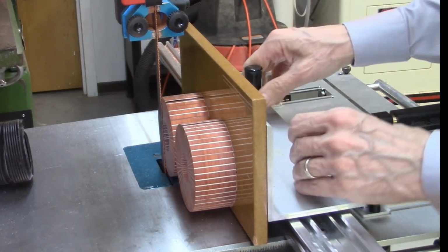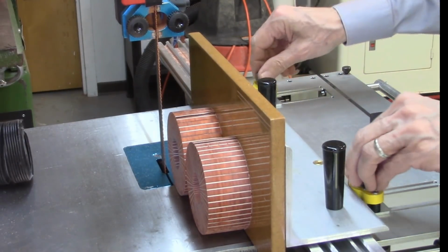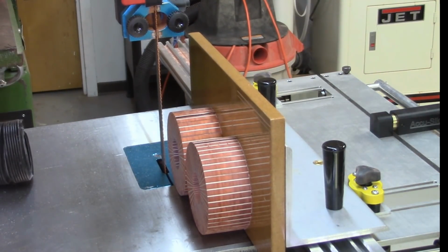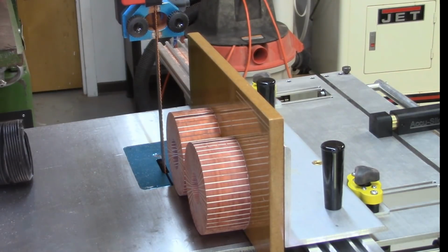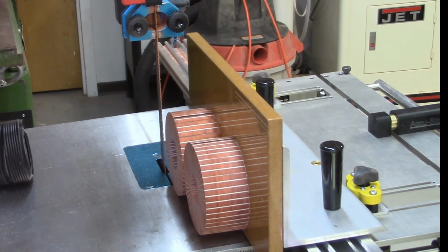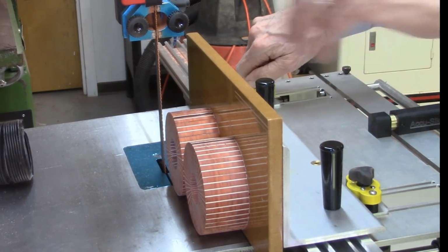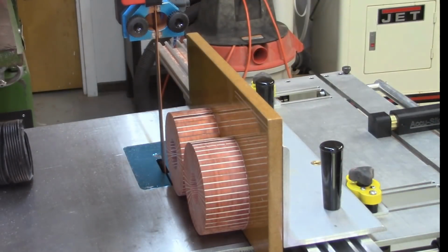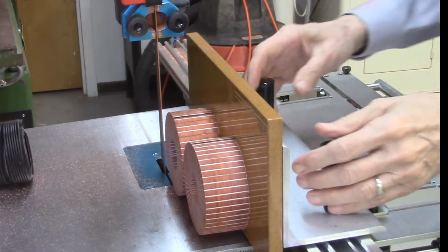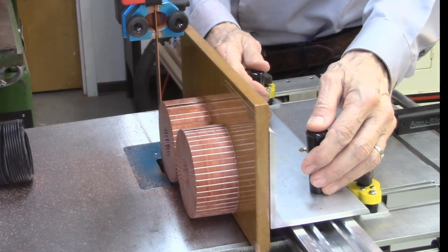The segmented discs are moved back away from the bandsaw blade, and the index wheels advance 1 full revolution to allow for the bandsaw blade curve. The index wheels advance 1 full additional turn to provide for the first cut, and the mag jigs are locked in place. The purpose of this first cut is to true up the surfaces of the disc so that all future cuts will be perfectly parallel to the surface.